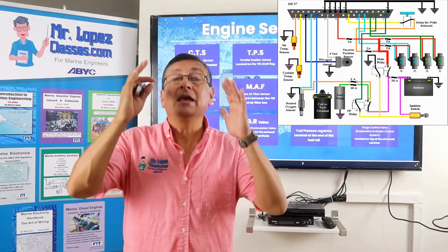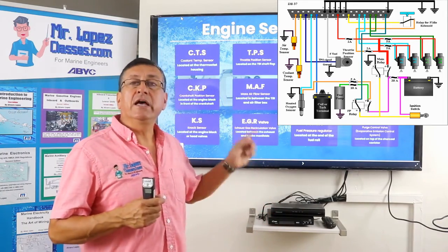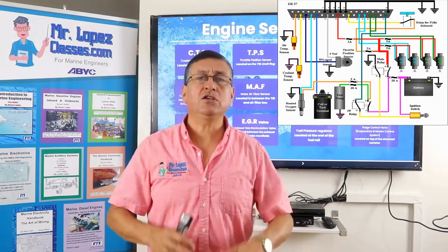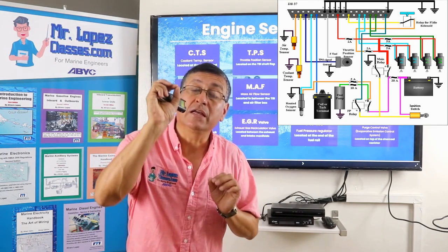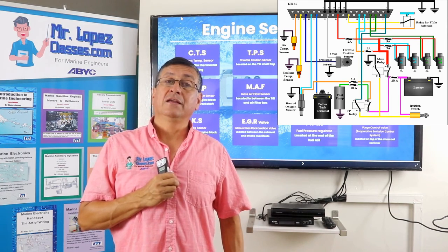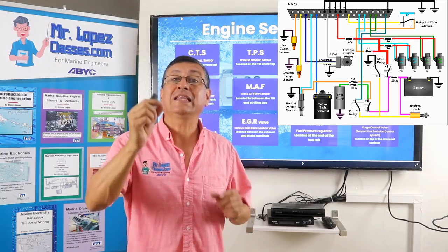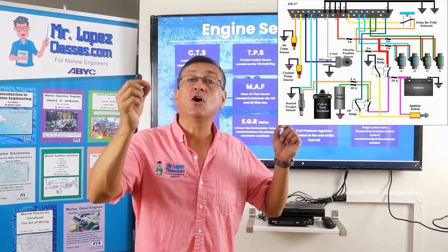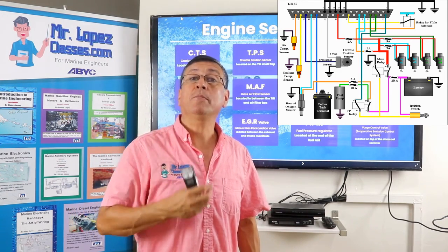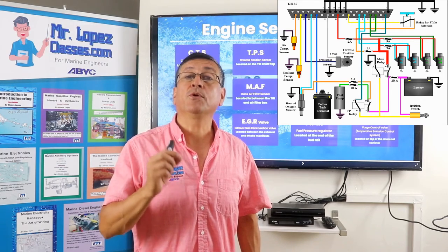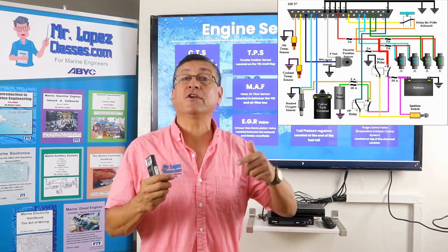At the end of the service manual, you find a wiring diagram similar to this one for each engine, and you can identify which is the pin in the computer dedicated to that sensor, and you can follow that cable, and you can identify continuity in that cable, and you can verify if the output coming out from the computer is okay, or if the return from the sensor is good.